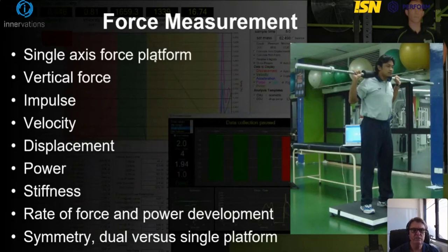the main reasons is that single-axis force platforms are now readily available. They're much less expensive and easier to use. They're more portable than the typical biomechanical triaxial force platforms. Triaxial force platforms, generally used for biomechanical analysis, are really overkill in the strength and conditioning field, because the single-axis performance platforms only measure vertical force, or force perpendicular to the plate surface.